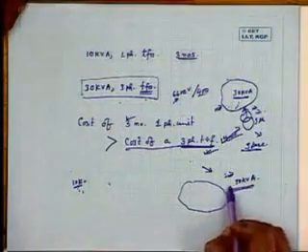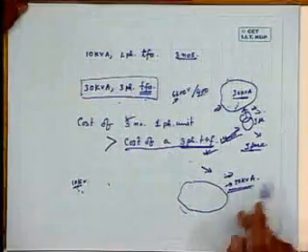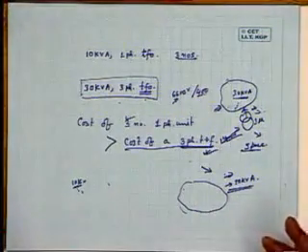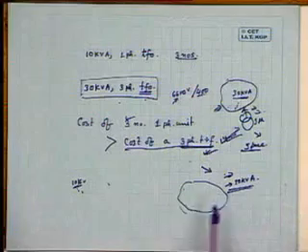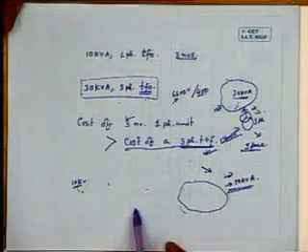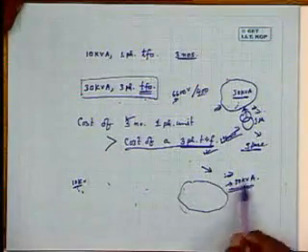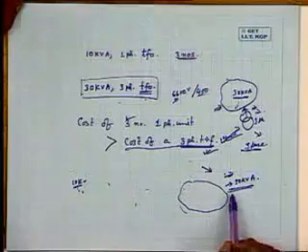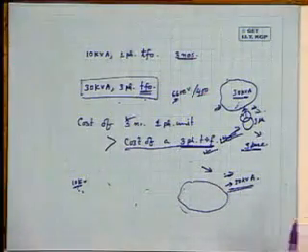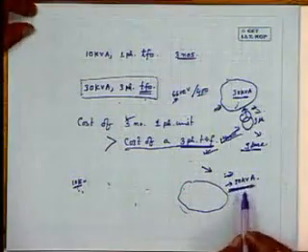Some small figures I am taking, it may be slightly higher. The projected load of this particular area is 30 kVA. A few consumers are right now present, maybe totaling about 15 kVA. Now, it is of course futile to buy a 15 kVA transformer right now and start supplying, because within 2-3 years the kVA rating will go up further.